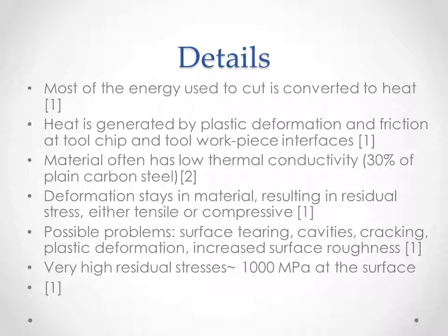Another strike against these materials is their low thermal conductivity. So it takes this massive amount of energy to cut, but coupled with this low thermal conductivity, you can see they're about 30% of plain carbon steel, and we have a lot of localized heating.